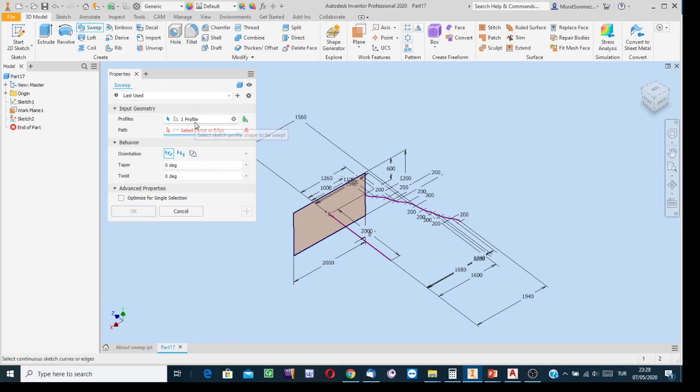Well, profile, yes, automatically sensed. Select curve, say, to indicate the path. This is the display to click. It is going to be automatically clicked by the software in order. If there is a blue shading along the boundary of such a monitor, then this means it has been toggled on. So well, here the path is not this curve. Path is this straight line indicated.